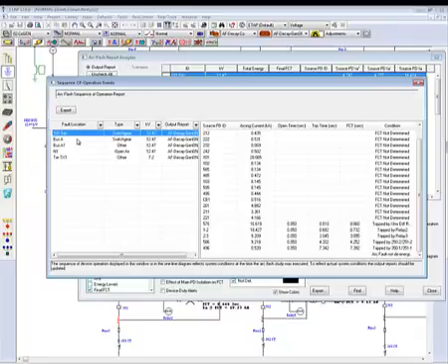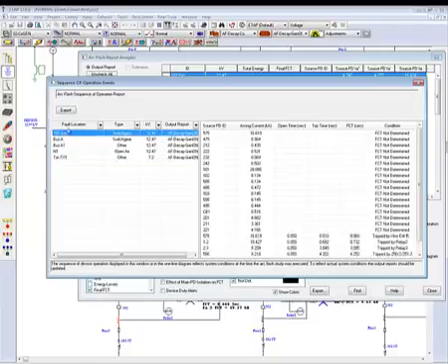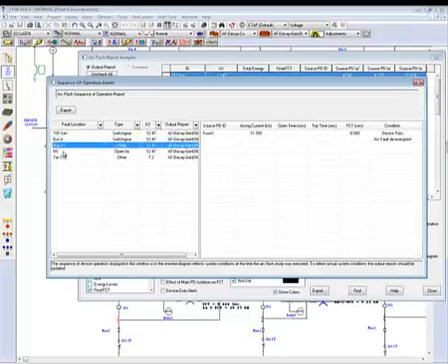Now let's go to a different fault location with a different kV, and you see here that the operation for this tertiary transformer 1 will be 476 breaker and 576 breaker, and these of course are transformer differentials, and the arc fault has been de-energized. Now the great thing about this tool is that you can export it to Excel and have a list of the operation of your devices for this project, and you can then also troubleshoot some of the fault clearing times not determined.